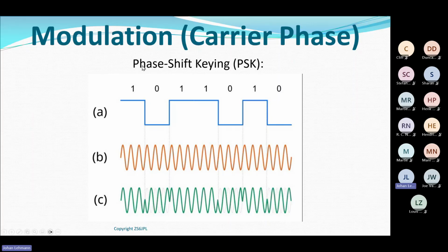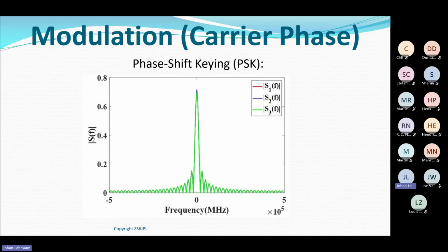That is why they call it phase shift keying, because I shift the phase every time there's a state change. It's very efficient. If I look at the spectrum of a PSK signal in the frequency domain, you'll see a nice sharp carrier frequency and very little harmonics going down. So again, it's an efficient way without a lot of wasteful expenditure going on. I hope that one got home.